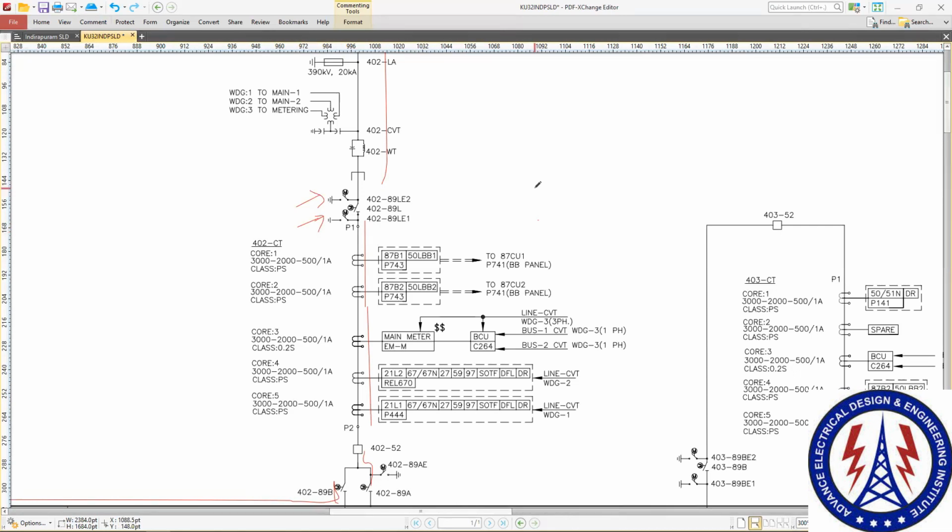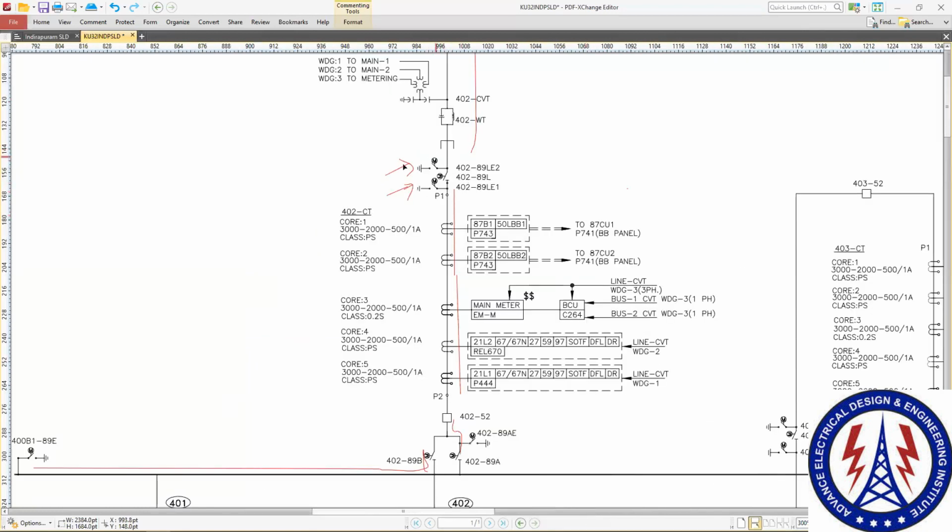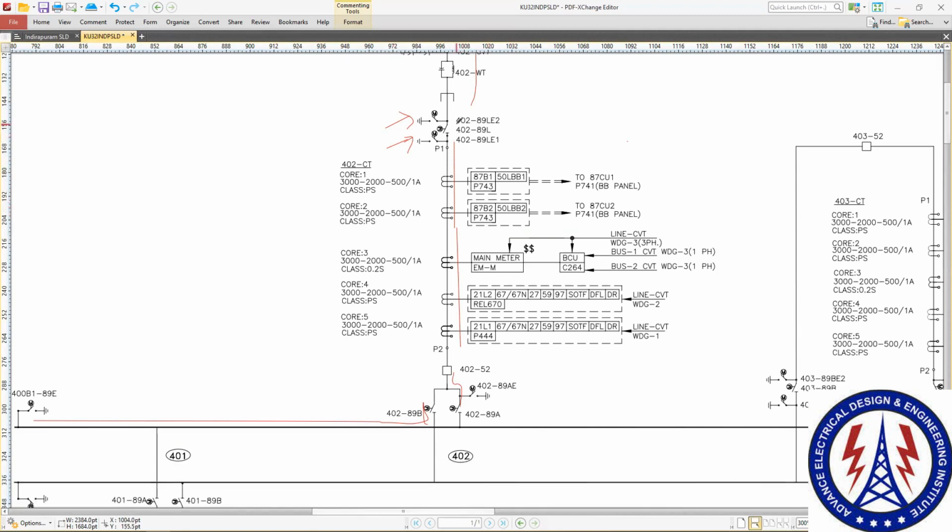Yes, sir. So that is why for each part one earth switch is required. In this way we provide an earth switch for each and every part. Suppose you trip this circuit breaker, this becomes normally open. So this above part and this part will be two different parts. Then you open this isolator, then again this part will be separated, and this part becomes another, disconnected from the above and from the ground downside.